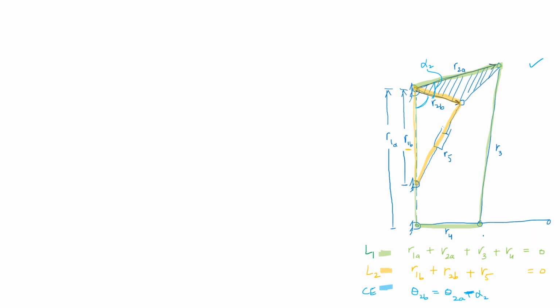The problem is to find out velocities. Velocities have been selected because if you know the procedure for velocities, you can obviously move one step further to find accelerations as well. The procedure is not going to change, so velocities cover all the basics that we wanted to cover over here. For velocities, I need to have theta 2a dot known.